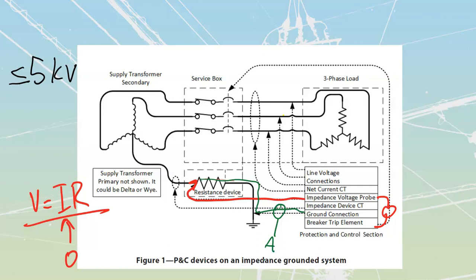We put what we call supervisory current. That supervisory current is going to flow all the way through here and gives it a very, very tiny voltage rise as a result of it going through there, which this voltmeter is then able to read. It's going to note that tiny voltage, so I'm going to just call that tiny voltage equals good. It's a good thing for it to have a tiny voltage, and it's monitoring with that ammeter as well to make sure there's continuous current through it.